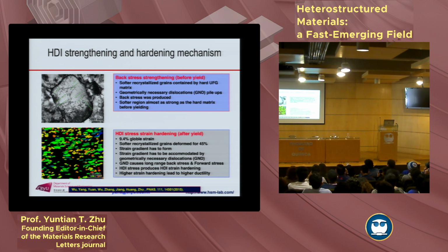So we said this ideal stress is very abstract, hard to understand. But if we look at this, this is one large grain, about 4 micrometers. And look at this dislocation piling up. Each of these blue lines has one dislocation piling up. You think about this. When you try to apply stress to it, this large grain will activate Frank-Read sources. The dislocations will try to pile up against this boundary.